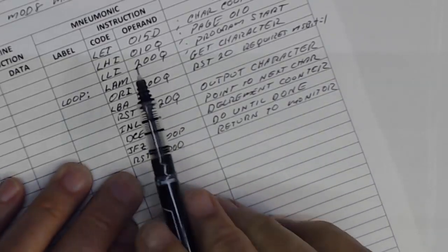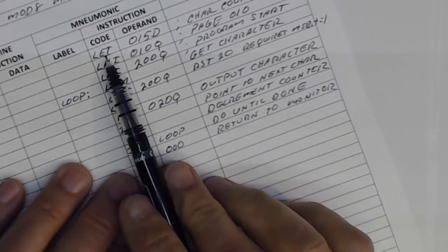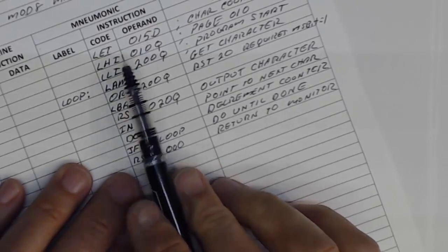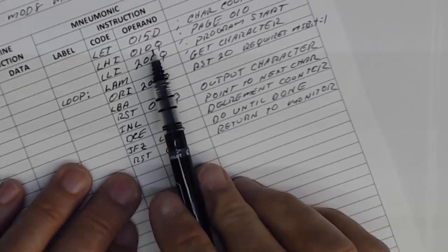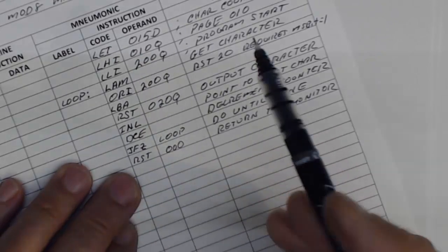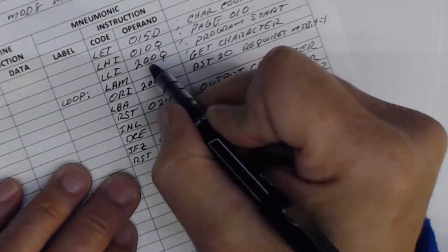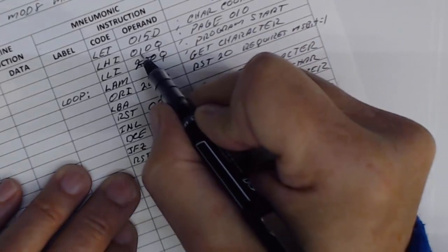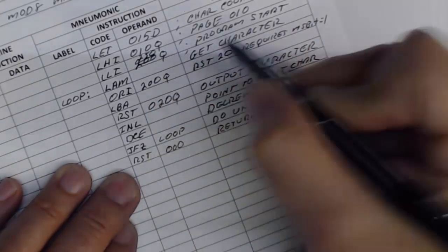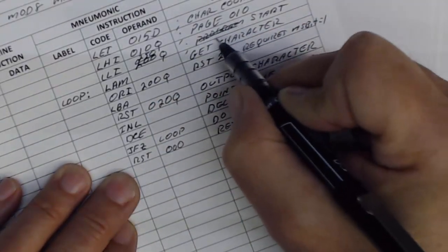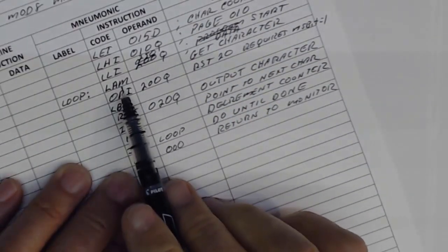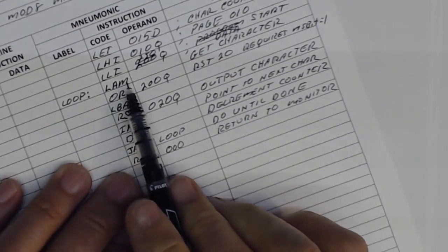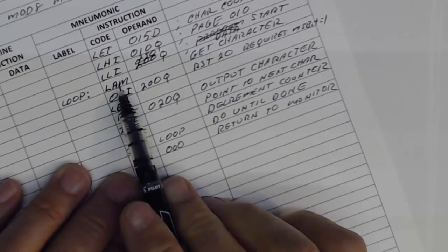Okay, so let's load our program again. We're going to load into the E our counter of 15. We're going to load the HL register pair with our address, which is 010. We didn't want to load 200 here. We wanted to load 250 because that's our data. That's not our program start, that's our data start. Sorry about that. We then want to move from the memory into register A, so we get our character.